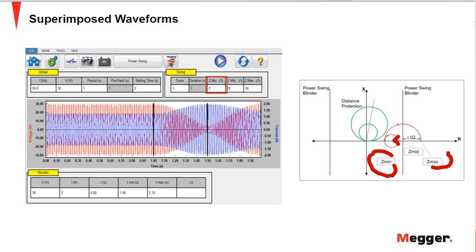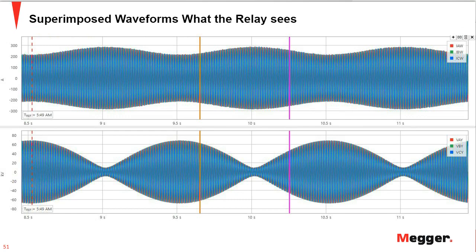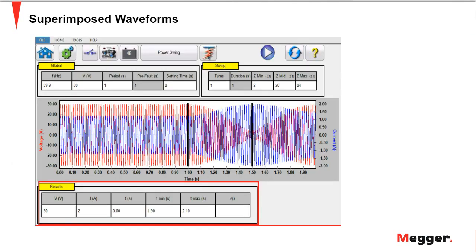Okay. So after that, I just can run the simulation, and for example, this is a capture that I did here this morning with a relay of the actual waveforms that you see coming out of the test set, and this is how the relay will see it. This is an actual COMTRADE that I captured at 4 kilohertz. I just did a capture of 3 seconds of that oscillation, and there is also a tool to test.